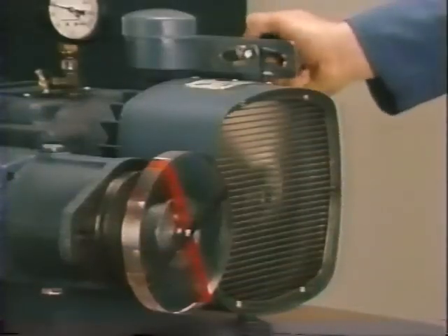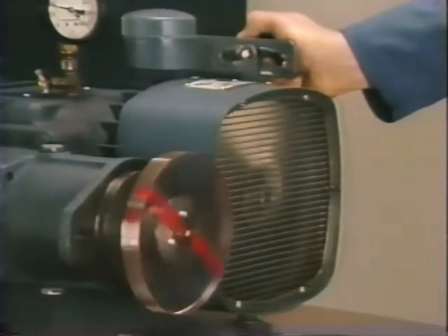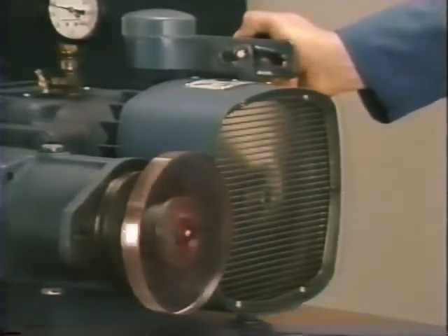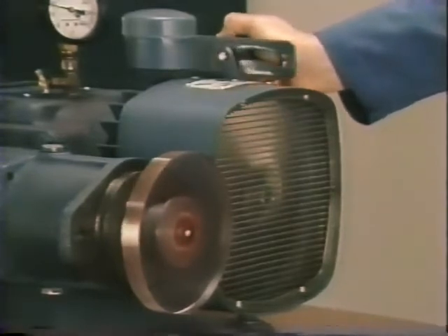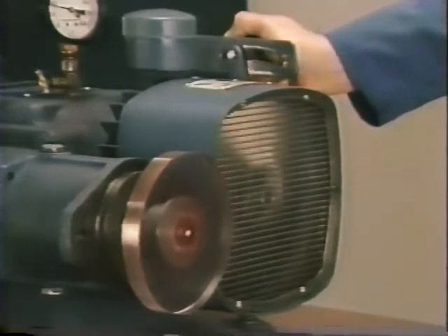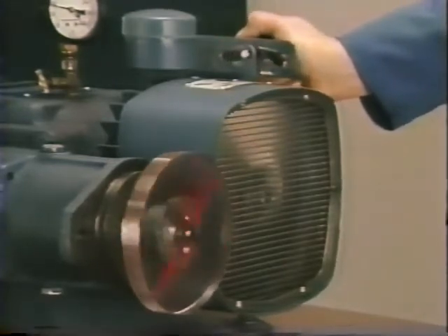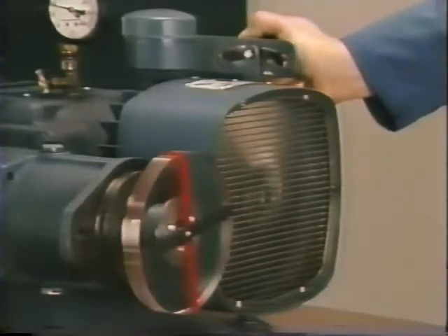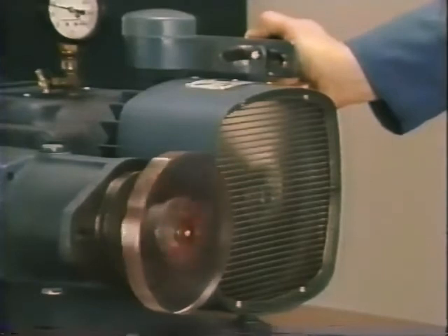Moving the lever off-center causes the motor to rotate slowly. The more we move the lever, the faster the motor runs. How fast the lever is moved determines the rate of acceleration and deceleration of the motor, and of course, crossing center will make it reverse. Remember, the pump and motor in this unit have the same displacement, so the top speed of the motor would be essentially the same as the pump drive speed.